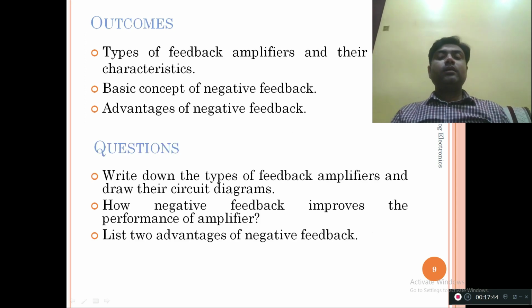What we have discussed in this lecture is the types of feedback amplifiers, their basic characteristics, the relation between the input and output impedances and how they are related with the source resistance and the load resistance, and the basic concept of negative feedback and how it helps improve transistor and transistor amplifier characteristics.